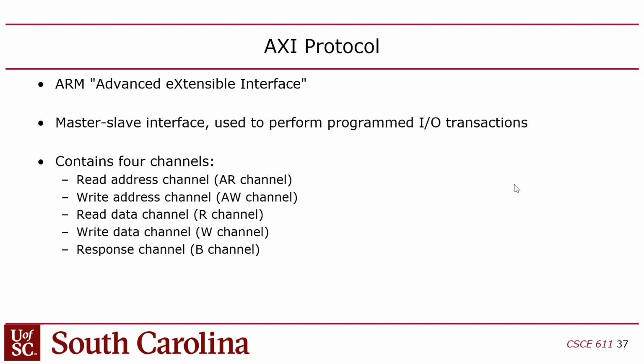So instead of a shared bus, there are these arbiters, these switches, well, they're actually crossbar switches, where the master has a port on that switch, and the switch is aware of what the address ranges are, what the I/O ranges are, and based on that address, it'll route the request to the appropriate output of the switch, and it just goes to the one peripheral. Okay. That way you can have multiple things going on at one time. Yeah, right? And all the connections are point to point. So everyone connects to a switch. Everyone that wants to communicate on AXI will have one connection to the switch, and everyone that wants to receive a request from AXI has one connection from the other side of the switch.